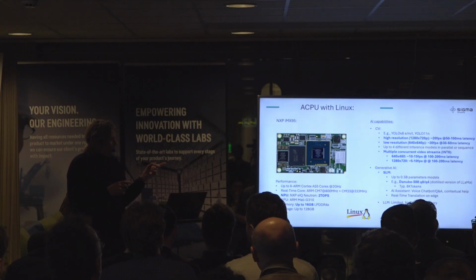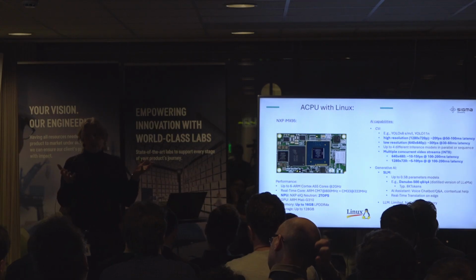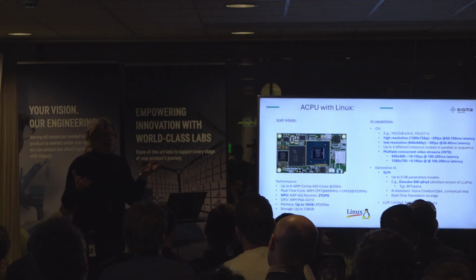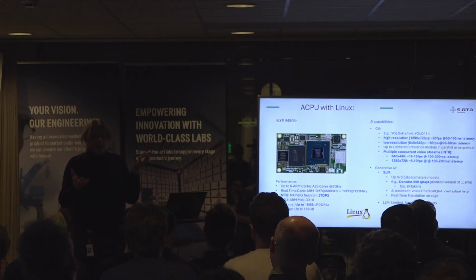This is how many processing steps the AI engine can run. And this is one area where people are mistaking themselves. So if you compare 2 solutions, so this has 100 TOPS and that has 2 TOPS, then this must be like 50 times better, right? And that's not true, really. It's a clear sign that this is better performing than that one. But if you, on the other hand, have a slow memory access, so the DRAM bus system is really slow, you'll have a lot of latency.